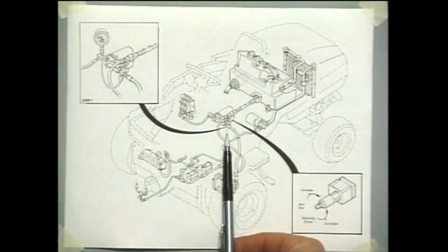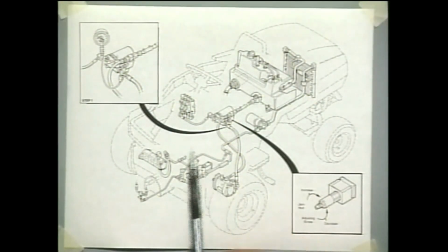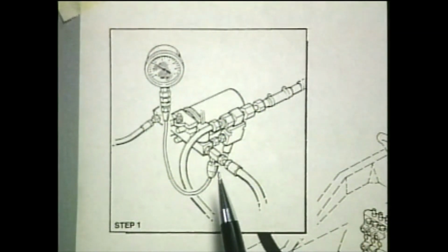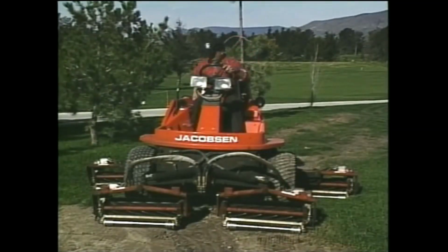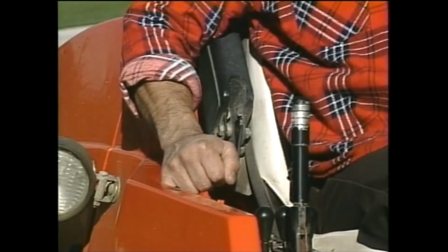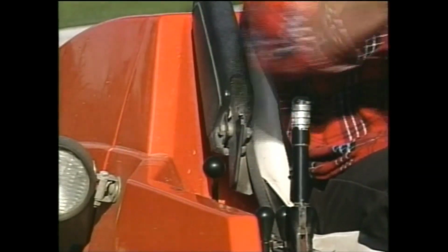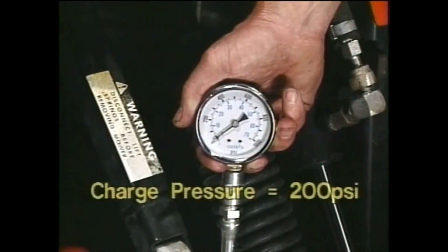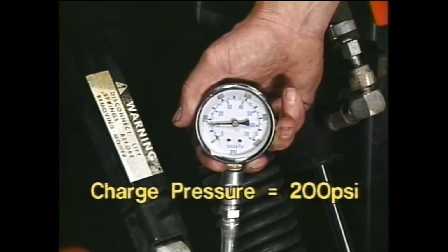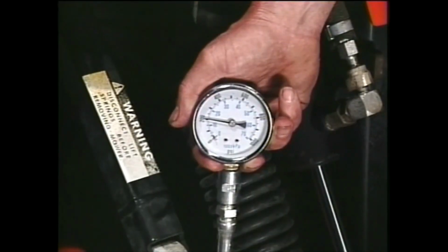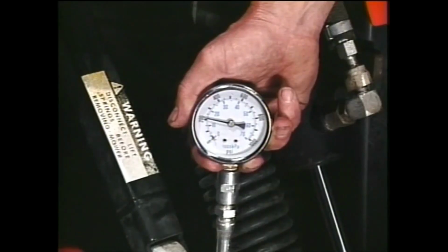To test the charge pump pressure on a hydrostatic transmission, first look for a test port provided by the manufacturer. If one is not provided, install a T-fitting with a gauge. To adjust the charge pump circuit relief, warm up the oil to 120 degrees, then raise the RPM to the maximum governed speed. If the pressure is incorrect, adjust the relief valve by slowly tightening the spring to increase the pressure or loosening the spring to reduce the pressure.